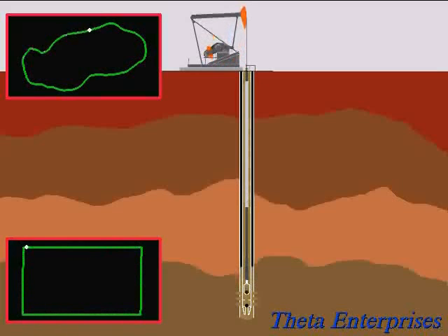What's the little bounce that you're talking about? Actually, that is not a bounce in position, but rather a bounce in load. Because remember, waves are moving up and down through the rod string, and as these waves reach the pump, they can make the load fluctuate. So you see sometimes what looks like a bounce, like right there, and it's simply a fluctuation in load as the waves hit the pump.